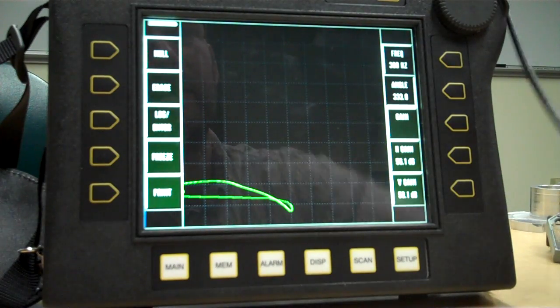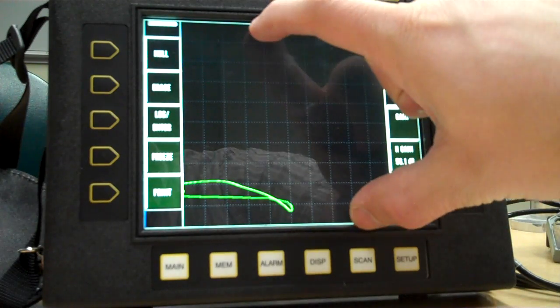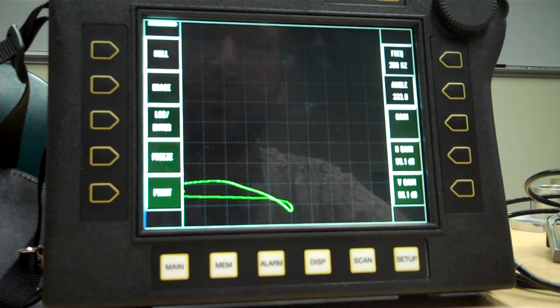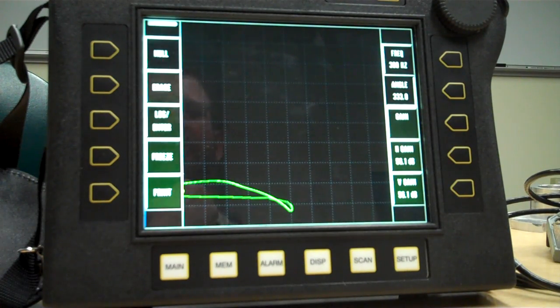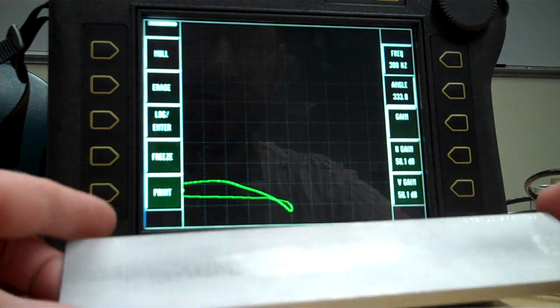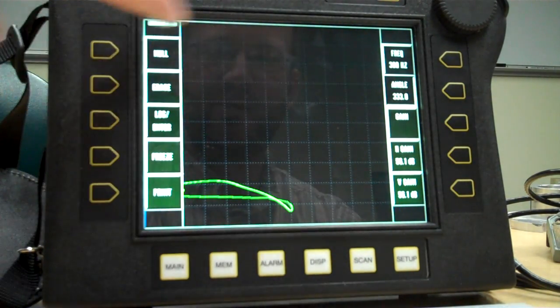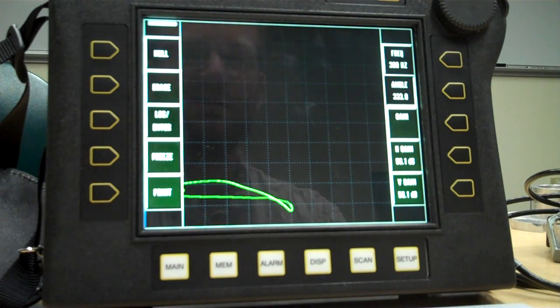Whereas when we took the frequency and raised it up and we were around 3 kilohertz, we saw a nice big spread here for all those different thicknesses because we were pretty much set for that standard depth of penetration. So just something to think about when you're testing your frequency and what that actually does with your conductivity curve or what that does with your thickness line. But this is a common application, testing for material thinning on the back side of a piece, and you can't see the top, maybe it's corroding from the back side. You just know that that thinning line is going to come up like this. So any point on there tells you, okay, well that material's gotten thinner, I've lost conductivity. Okay? So, something to think about.